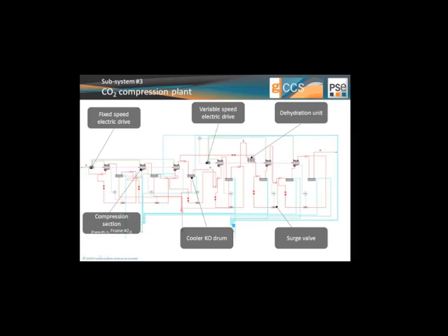You can also observe that whenever we have a draw of material and a cooling section or a knockout drum, we have a compressor section, and then obviously for the purpose of control, surge control, we'll also have recycles implemented and surge valves that would open whenever the compressor section gets close to the surge limits. There's a very basic dehydration unit model here that simply computes the energy requirement for this step.